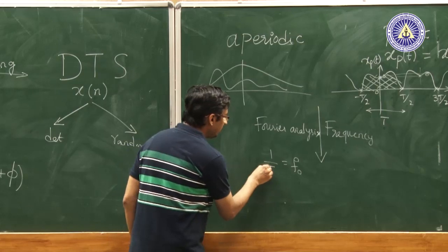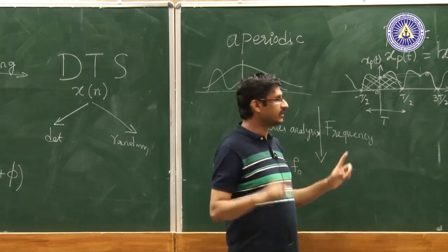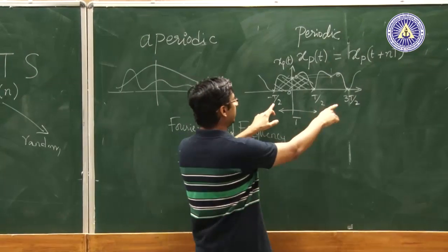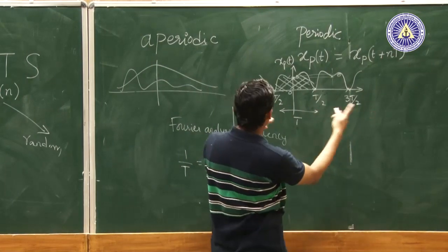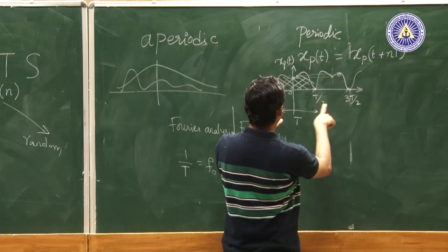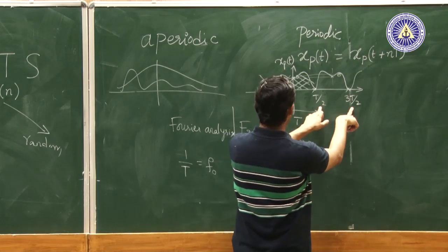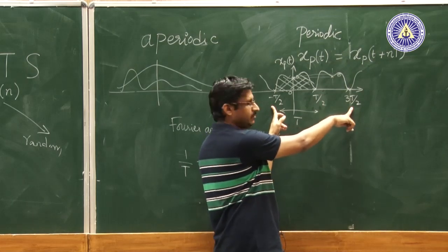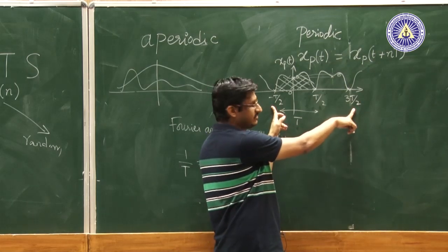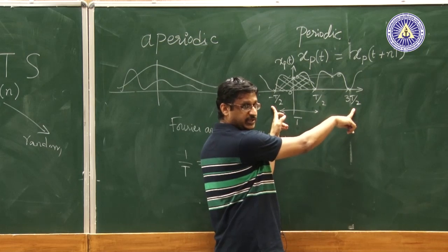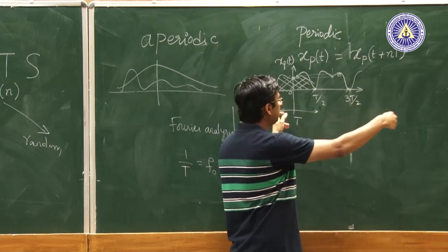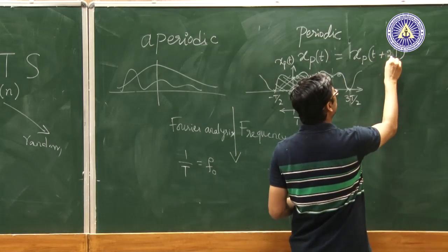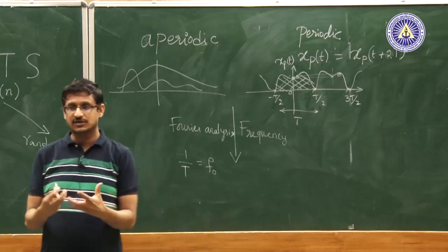And you can also clearly see that instead of thinking of the fundamental period as T, I could technically also think of this as a period of 2T. So, this is one picture. I can think of this as a periodic signal with a period of 2T, because in this one I can easily replace n by 2, and then the function is essentially the same.